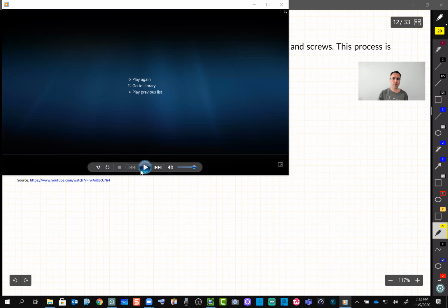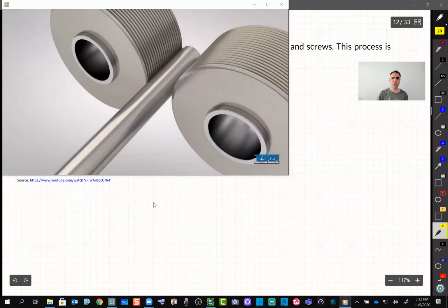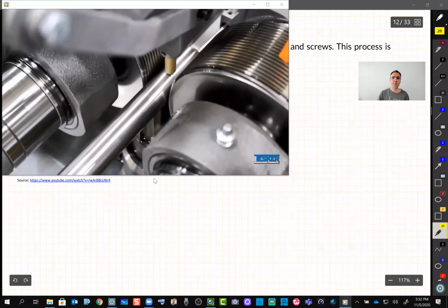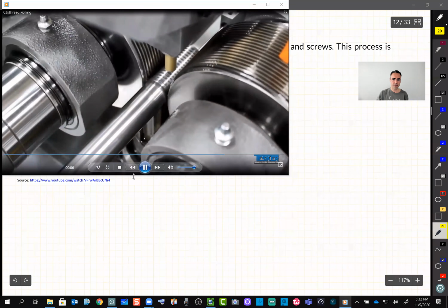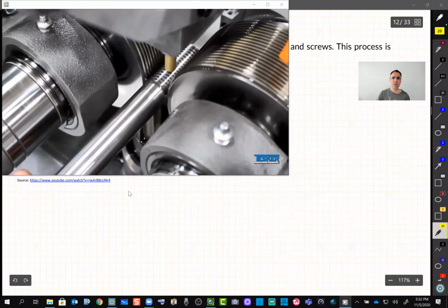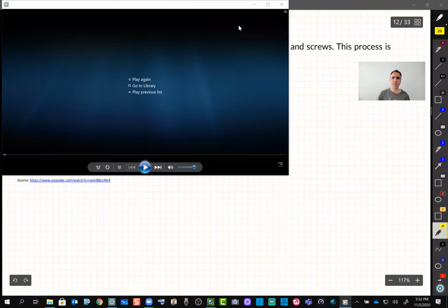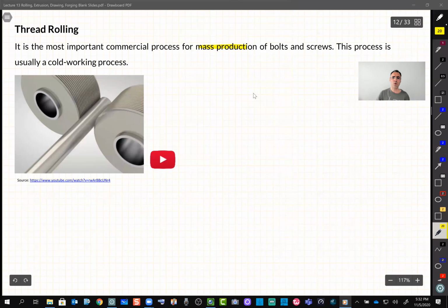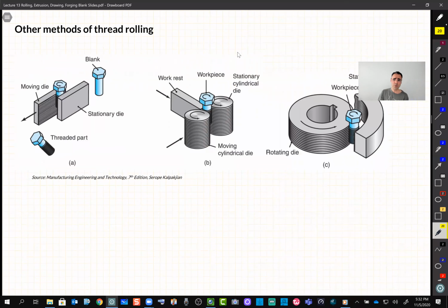It was very short. One more time. Two rollers, we have the patterns. We squeeze the cylinder between these two. And you've seen we use oil, constantly oil, to create the thread that we want. There are varieties of machines that you can use, and there is no particular difference in the final product. It's just a difference in the die.